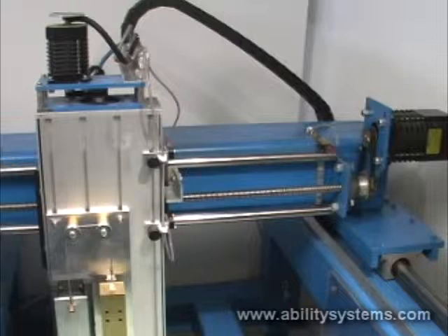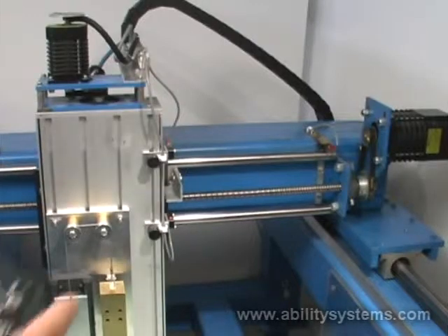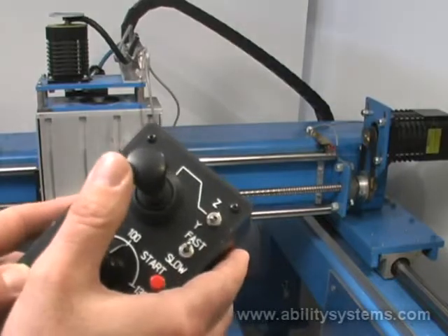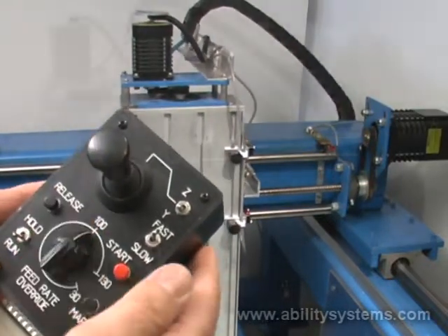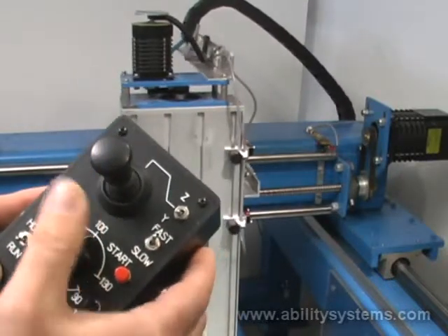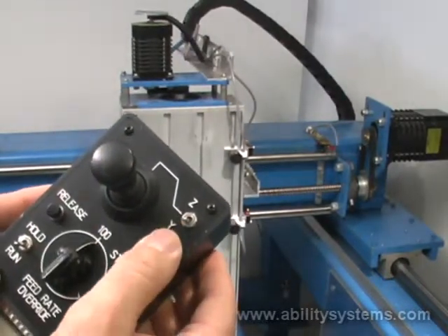Indexer LPT does not require switching an externally applied oscillator to the translator for manual controls. Instead, Indexer LPT senses the status of the joystick switches and keeps track of each pulse that it generates. With the fast option selected, the joystick accelerates the motor for rapid positioning. Some overshoot may occur during deceleration when the switch is released.